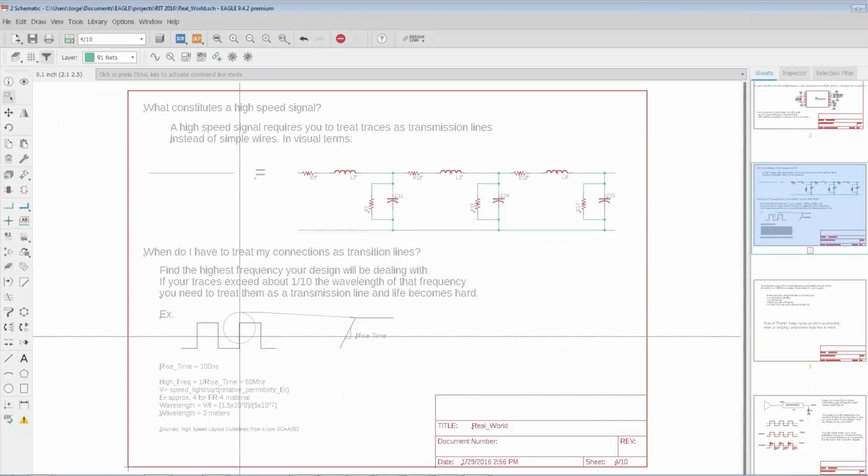What's the point of saying that? Okay, if you're working at a company and you're going to start making PCBs and you have high-speed signals, you don't want to lose a $10,000 run of boards, okay? So the best way to confirm the operation of your design before you manufacture it in the signal integrity world is you have to do simulation. So simulation is a big part of signal integrity design and analysis. There's just no way around it. Basically, that's the most accurate way to verify your design.